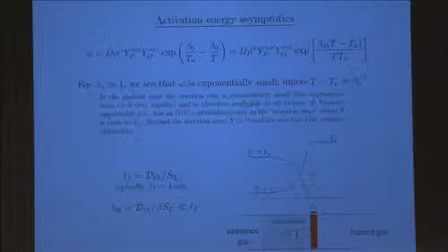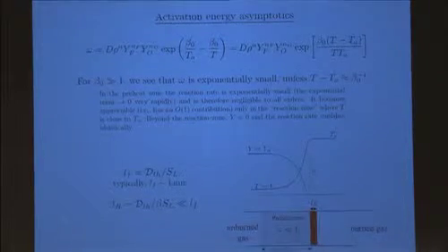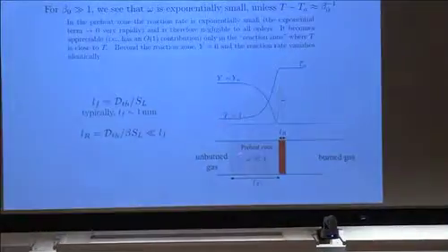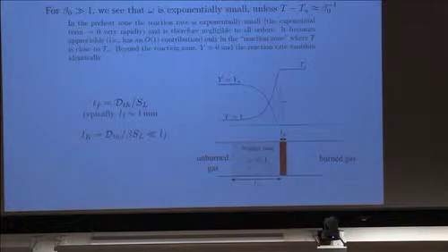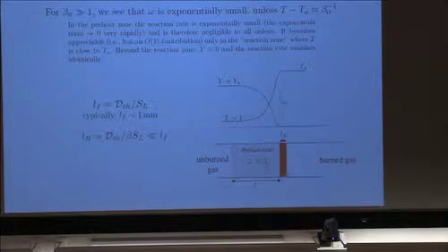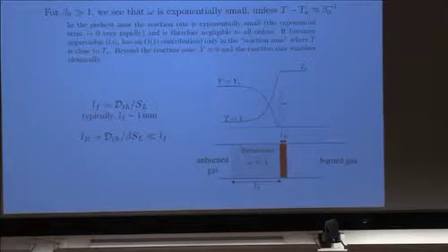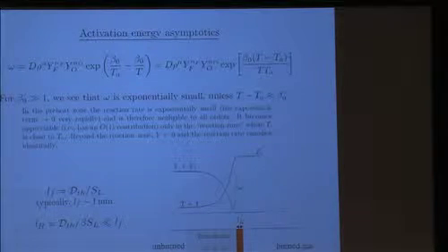And we have seen that since beta naught, which is the activation energy parameter, can be treated as a large parameter, then the flow field in general is divided into two regions. A preheat zone where the reaction rate is very small and negligible. In fact, it's exponentially small because you see the exponent written this way. When T is less than TA, the adiabatic temperature, since beta naught is large, tending to infinity, then this is like e to the minus infinity, which is approximately 0, very small. And so it's negligible in the preheat zone.